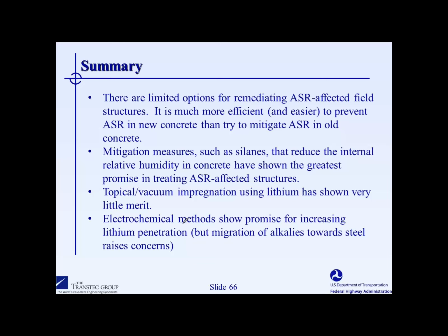Once we had the ground material, we extracted the lithium and tested it with the flame photometer test to measure the lithium concentration. We've done that at our different laboratories, and we've done some round-robin testing to ensure that we're all getting comparable values in terms of lithium concentrations. And the technique seems to be quite effective.